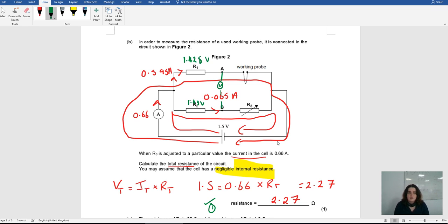Okay, volts. So what would happen is that, remember, this starts with 1.5. As you can see here, I'm measuring the potential difference between these two points. So my electrons come round and it's lost 1.3 volts worth of potential here, and it's got 0.7 left. On this one, it has lost 1.428, so it's got 0.72 left.